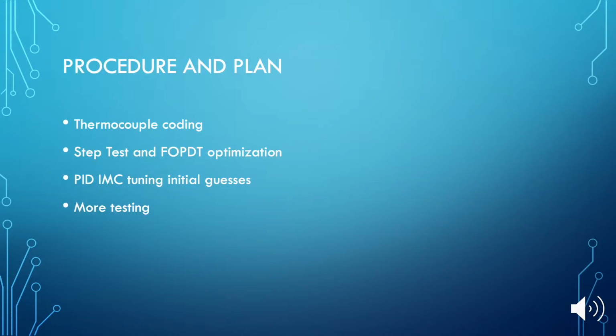Our procedure and our plan was first to figure out the thermocouple coating, do step tests and FOPDT optimization, take those to PID IMC tuning initial guesses, and then do more testing such as doublet testing.